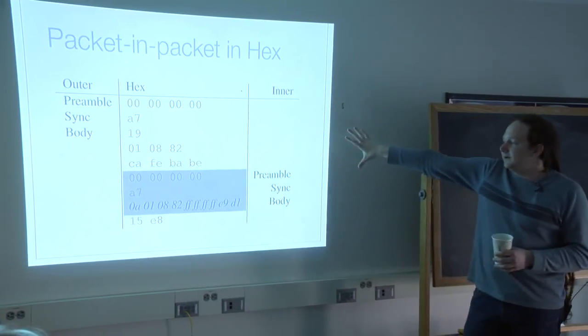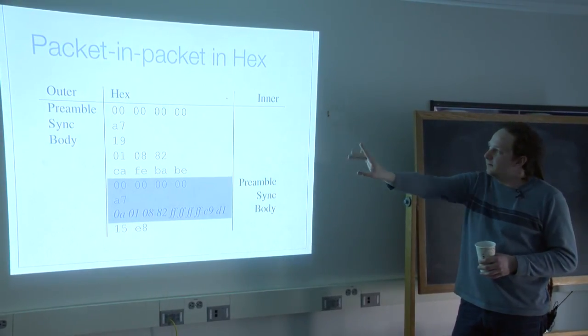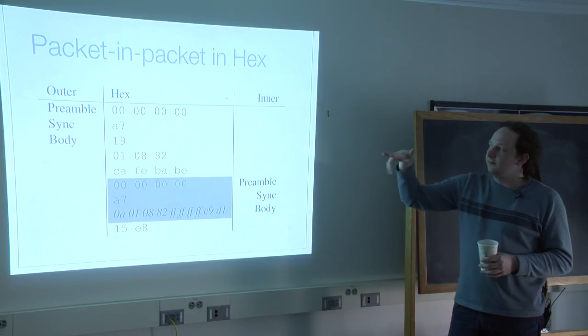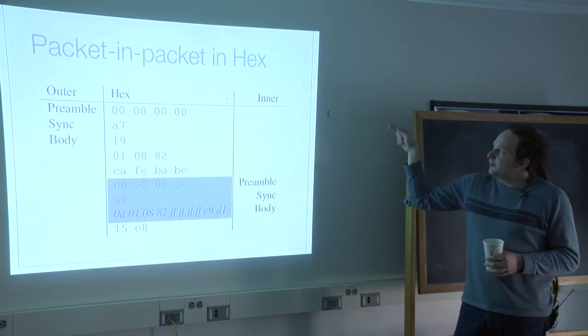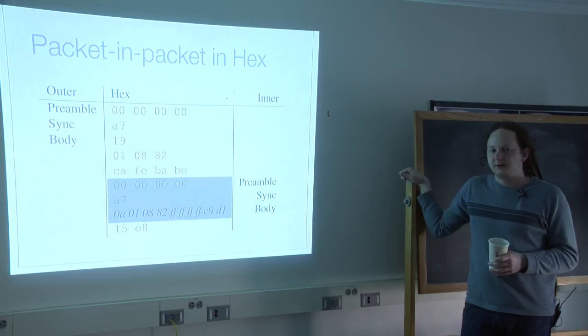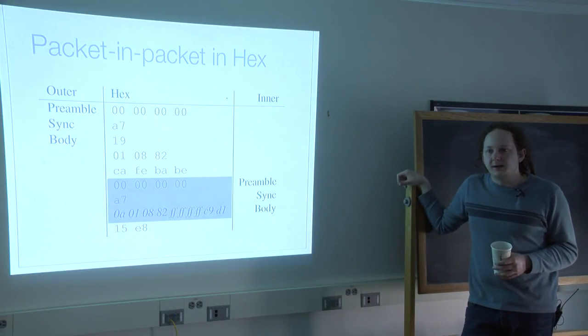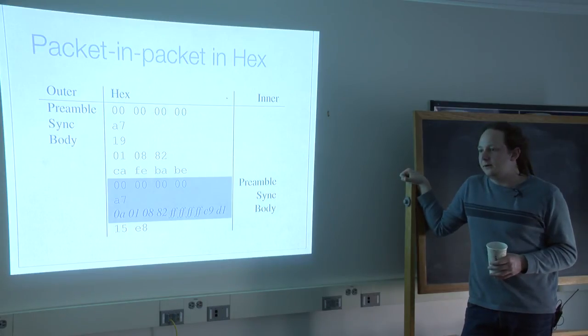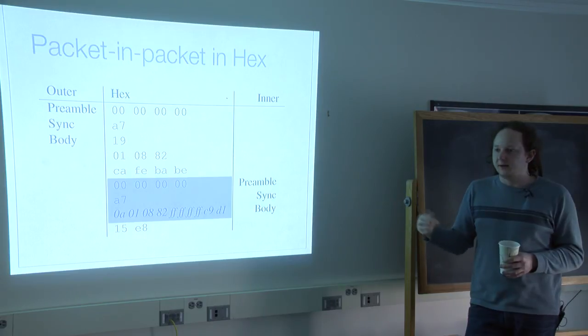So this is an expanded view of a complete injection, and you'll note that the leftmost column describes what the packet should be. This is the packet if there's no damage. The rightmost column shows what the packet looks like if the synchronization field is missed. Now, if you think of this as like the probability of that one symbol and no others being damaged by a random symbol error, this is terribly unlikely to work. Like you could retransmit it enough for it to work, but the odds are against you.